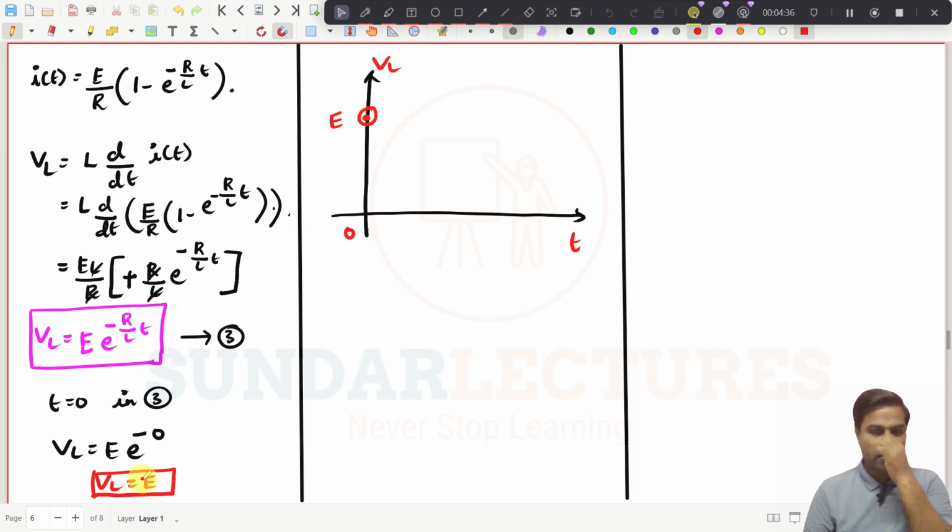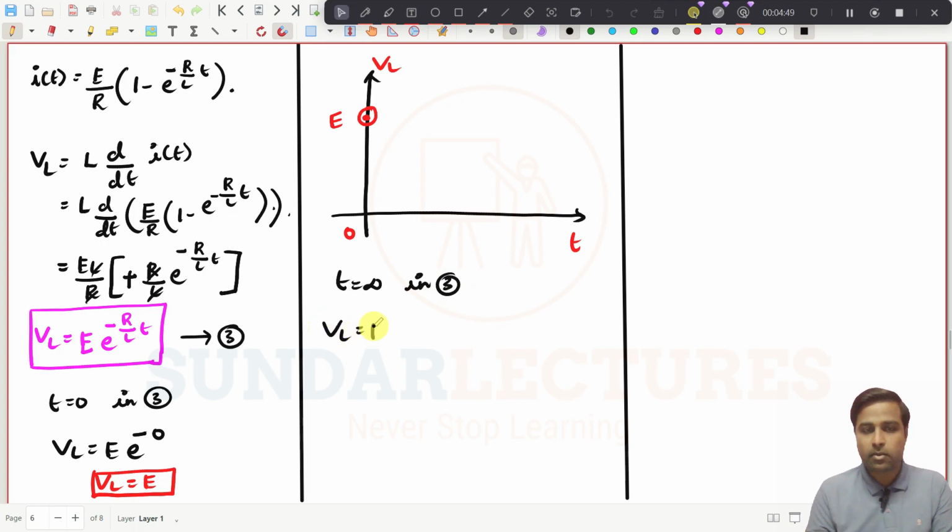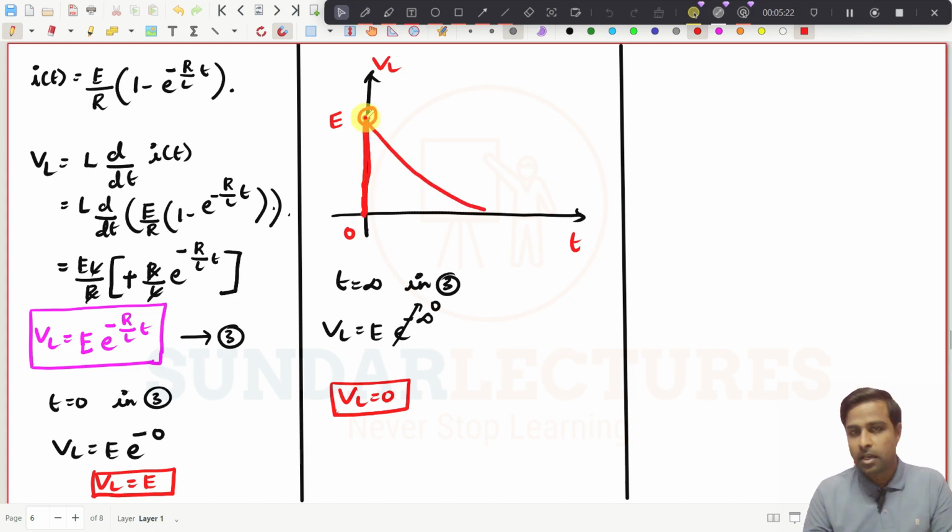at t is equal to 0 my value will become E, and if you put t is equal to infinity in expression number 3, what you will get? VL will be e power minus infinity, right? E power minus infinity will be what? It will be 0. Minus infinity will always become 0, right? So VL at last should be equal to 0. See, this is the curve now. So I will just draw. It will start from E, and then at infinity time it will become 0.